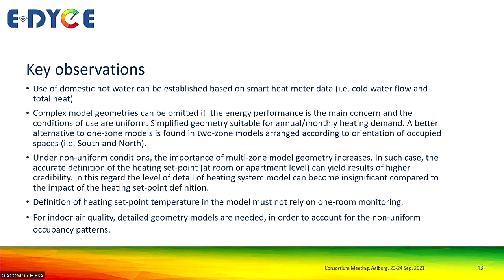That is also valid when we know very little about the occupant conditions within the building. If we do know more about our building operation and we have a possibility to define the heating set point, then we can benefit from going to more detailed models. And of course, one good learning from here is that defining the heating set point based on the measurement of temperature in one room might be more of a drawback than a benefit in our simulations.